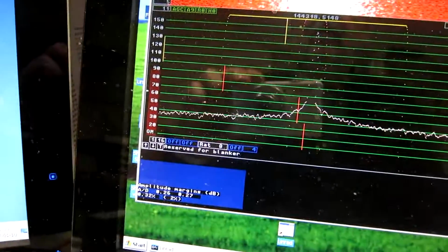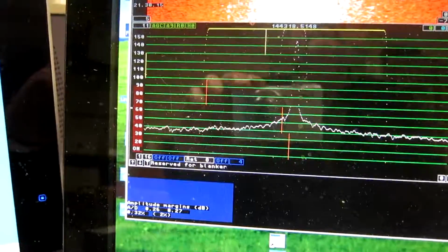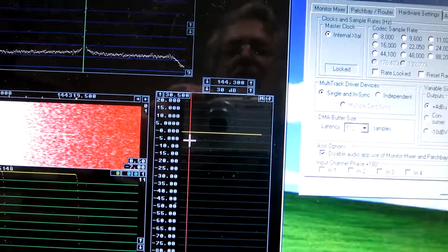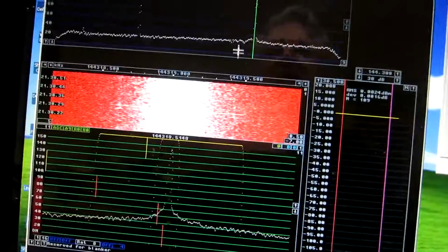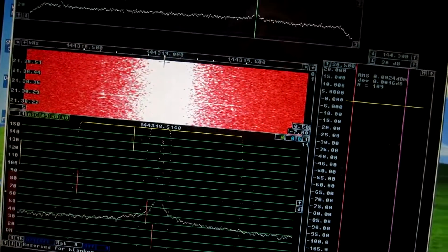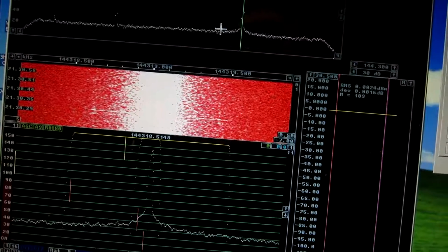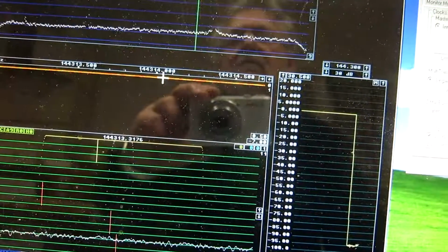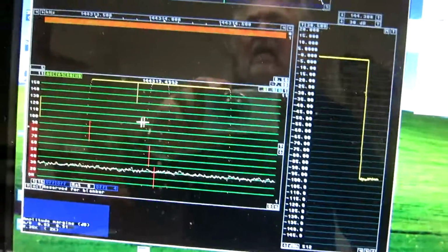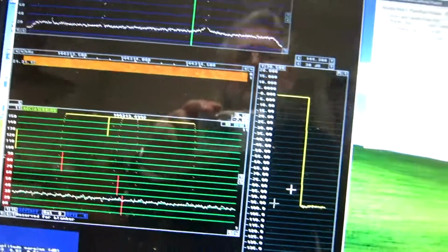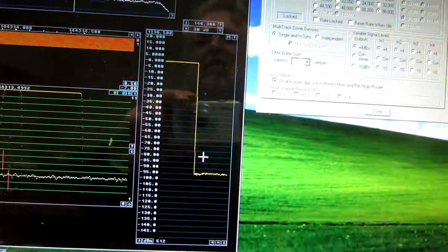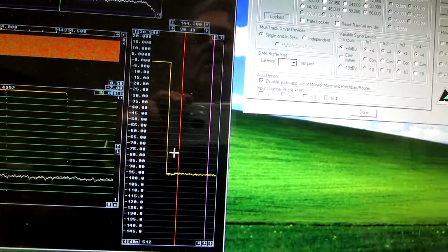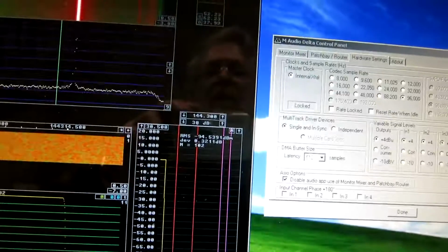The saturation is just a quarter of a dB above this signal level. And here is, and I have calibrated the S meter to show 0 on the signal. And I move 5 kilohertz downwards from here. That is 314. Well, that's here. And the bandwidth is 1 kilohertz. And I can read the noise floor in 1 kilohertz to, well, I had to wait, minus 94.5.